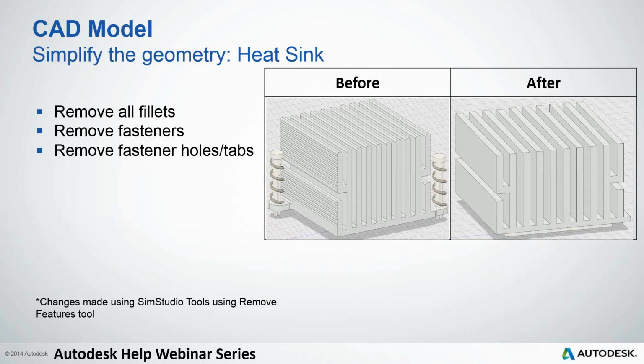a flow-through direction and use cross-sectional area parameters of the fins to get an approximate cooling and heat transfer capacity, and that'll allow you to have a much smaller element count, get simulations done faster, and all. In this model, we're not too worried about element count, and there's only one heatsink, so I'm just going to assign it to be aluminum and then mesh it.